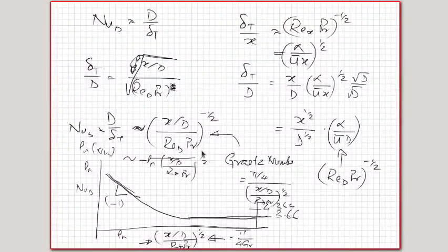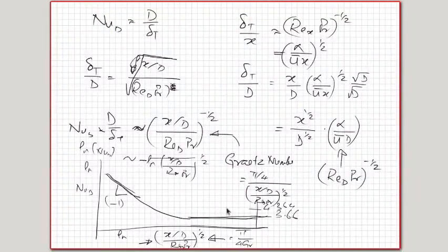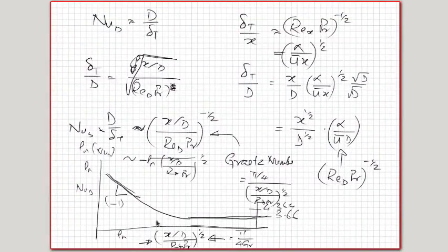And then as we go inside, as the boundary layer thickness becomes finite, there is a 1 by x kind of variation, hyperbolic variation. In this particular case, it is a 1 by x to the power of half variation that you see. Okay, so that is the expression that is shown here.